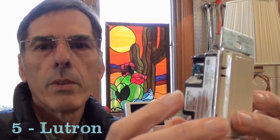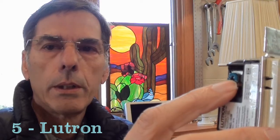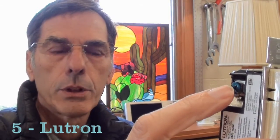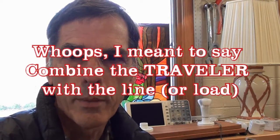If you have 3 or more switches, I have some concerns. Those concerns revolve around this blue connection. This is a control signal, and it's made to communicate between multiple Lutron dimmers. You can use this dimmer with a conventional 3-way switch, but the wiring is unconventional. You'll have to go to the other switch, combine the neutral and the line or the load together with a jumper, and put that jumper wire on that switch.